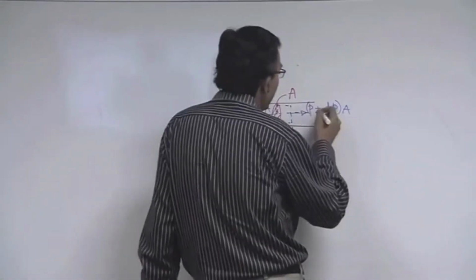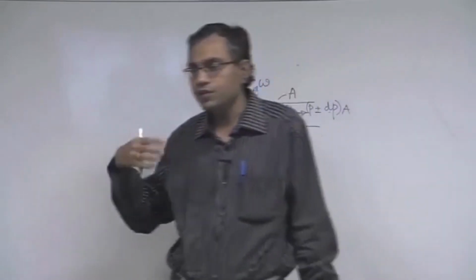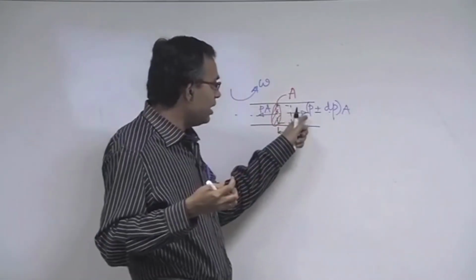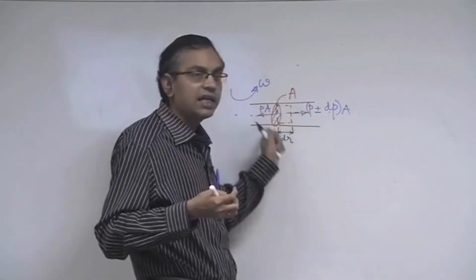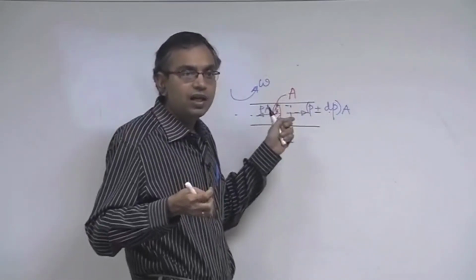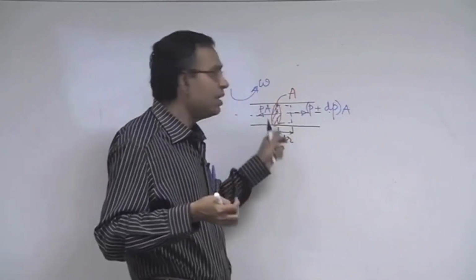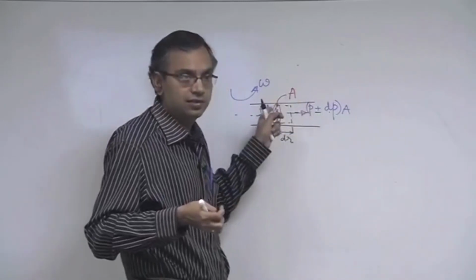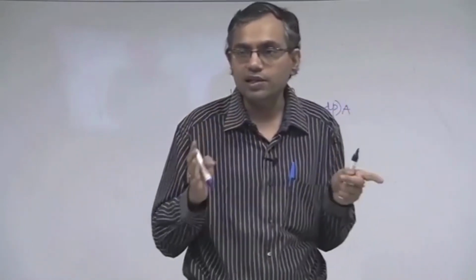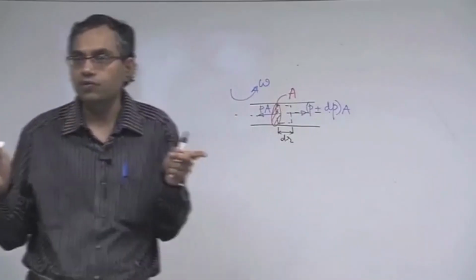So what is the difference between these choices? When you are considering the inertial force, you can write the equations of static equilibrium by referring to the inertial force as a force. However, if you are considering the inertial reference frame, then the resultant force will be mass into acceleration. So in other words, if you are writing resultant force equal to mass into acceleration, that must be from an inertial reference frame, and there is no question of inertial force.